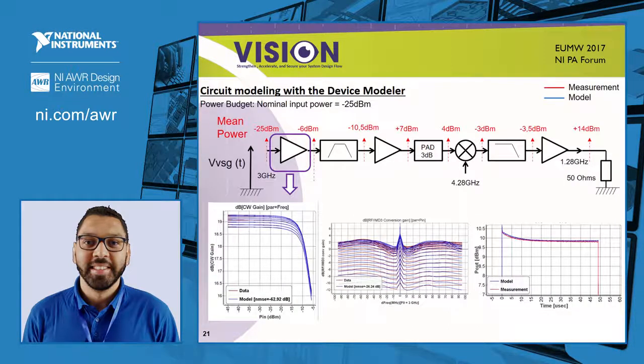The first component is the LNA that exhibits memory effects. The first graph shows AM/AM curves for different frequencies. This dispersion is called the high memory effect, and the model perfectly reproduces the measurement.